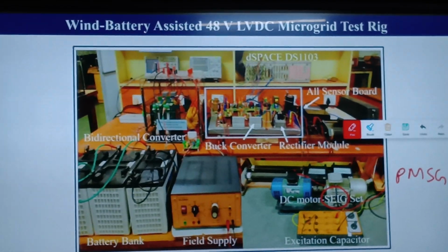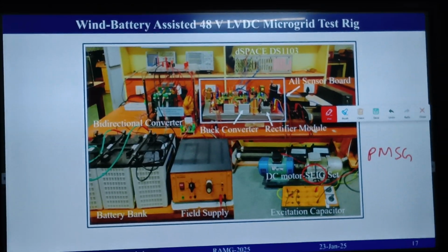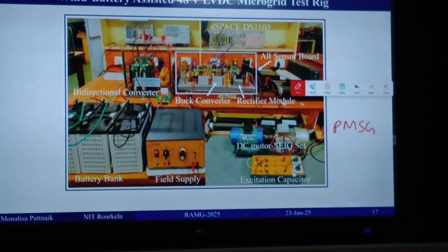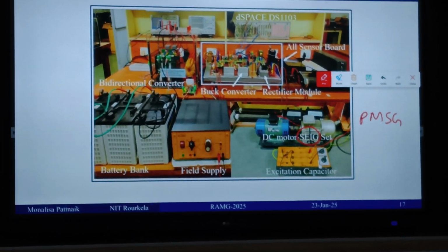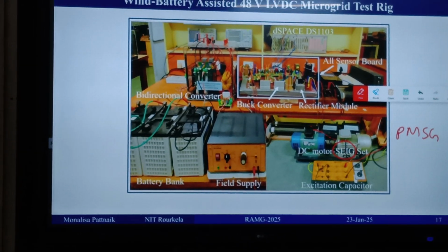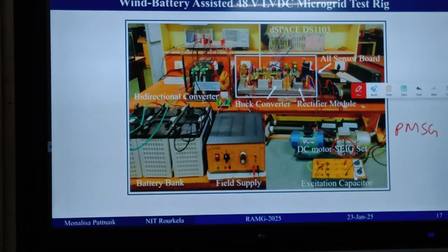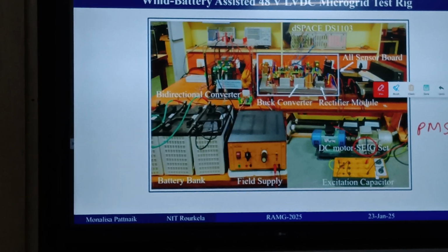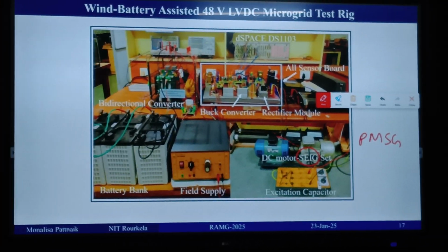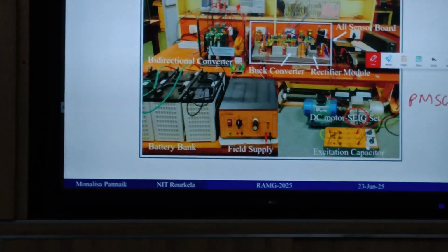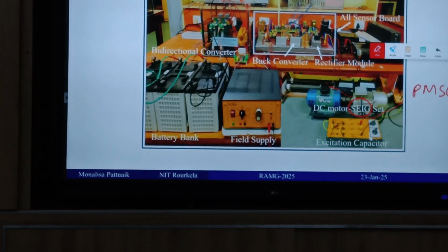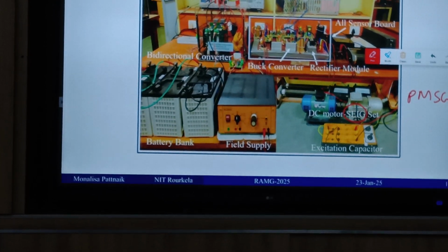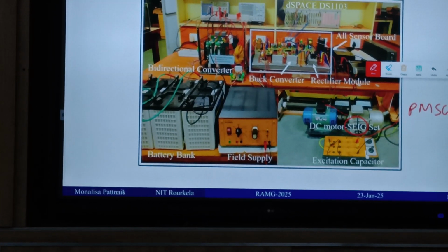Okay. So obviously based on your different machine, your control pattern output, this MPPT control technique remains the same. But depending on your output voltage and your bus voltage, you have to choose the corresponding converter, and accordingly you have to do the redesign. Suppose this is a 1 HP motor set, but after that I went for a 2 kilowatt or 1.5 kilowatt machine. So obviously all my design values will change again.